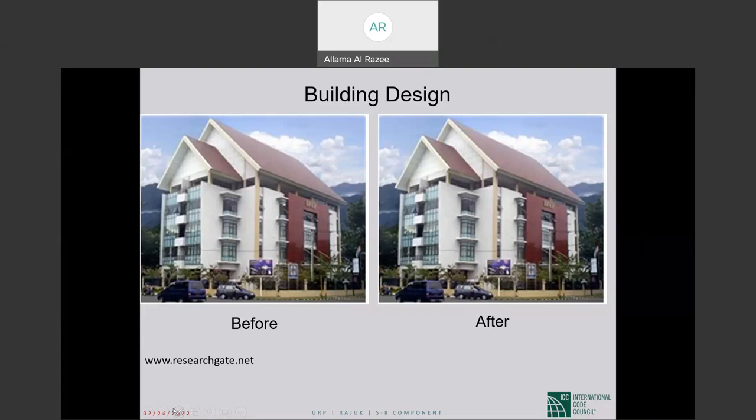Because the designer calculates the demands in all elements very precisely, and then we have good codes that for each element, each response parameter in that element can be designed in such a way that the capacity, the strength of the response parameter, is more than the applied.